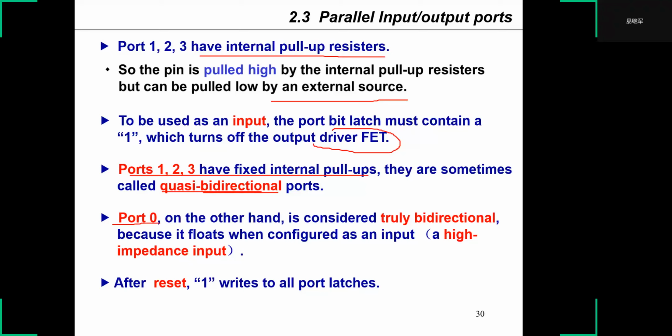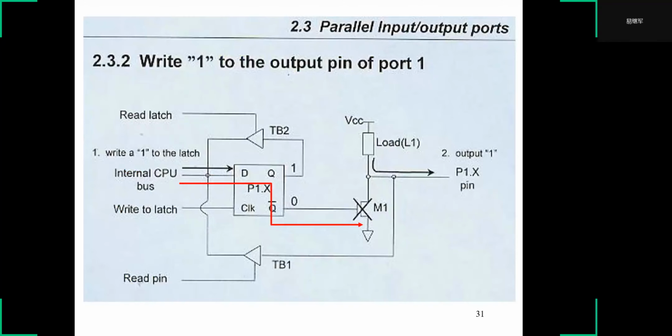After reset, one writes 1 to all port latches. When we write 1 to output pins of port 1, the signal flows like this.